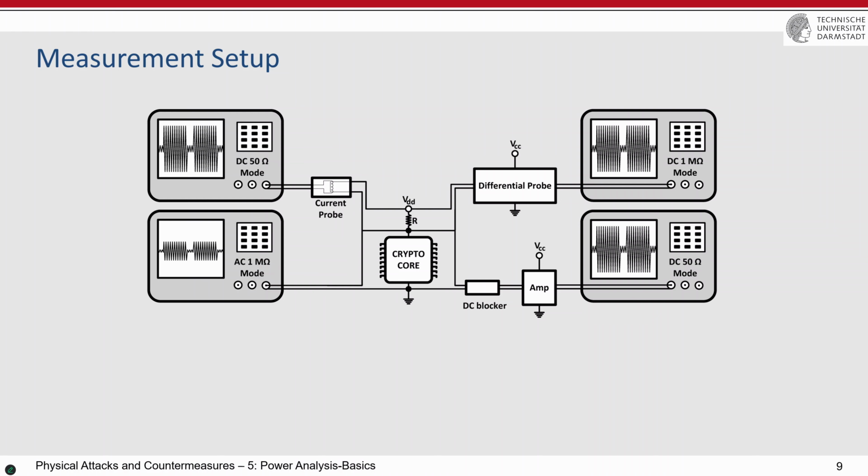I mean, when somebody designs a PCB, then you have to find out which pins are the VDD and then modify the PCB in a way that the resistor is placed in an appropriate way to be able to run the attack like this. Then it might be hard, in some cases even not possible, because the PCB has a couple of layers. And then the solution, if you do not have any option to put the resistor there, then you put an EM probe, electromagnetic probe, on the top of the chip, or close to the capacitors which are responsible for the VDD of the chip, and then you see somehow a similar effect.